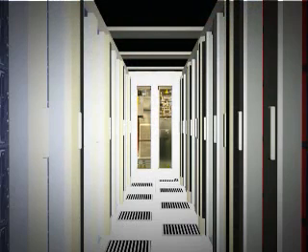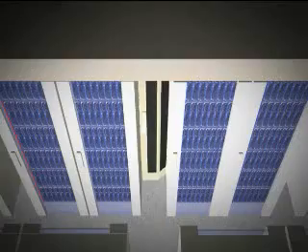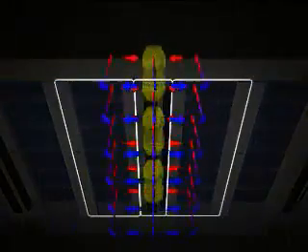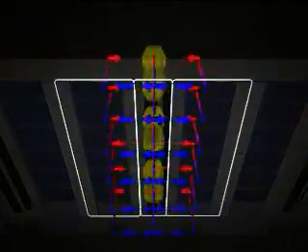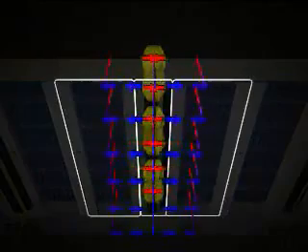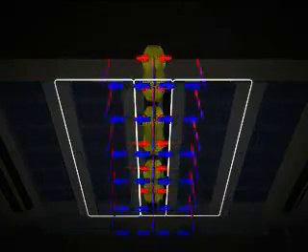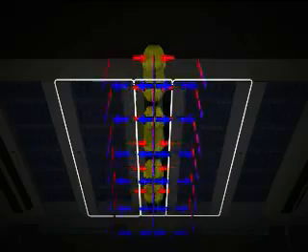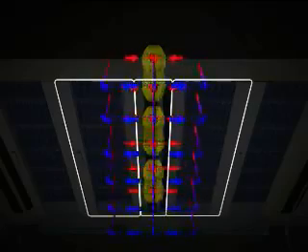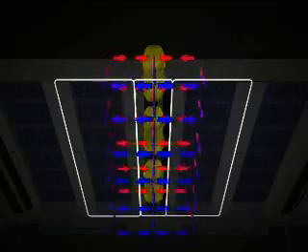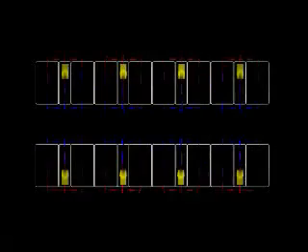Even in a site where there's no false floor, cold aisle containment shouldn't be ruled out. By introducing a liquid cooling package called LCP Inline, it effectively replaces the need for a CRAC system and provides up to 30 kilowatts of cooling per module. The LCP Inline still requires water as its cooling medium, and using an air-to-water heat exchanger, it blasts cold air into the cold aisle, where it's absorbed into the server inlets. To provide additional cooling capacity or even redundancy, it's simple to add additional LCP Inlines along the aisle, whenever and wherever you need them.